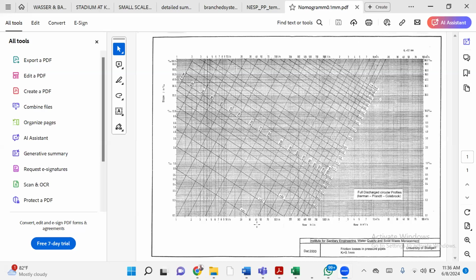Once I read this, I get 2 pipe sizes and receive 2 parameters from this. You will see that it's between this pipe and this pipe. I will choose the biggest, which is 200 mm. It means I need 200 mm to supply water to a 20 hectare district. And that is my primary pipe. When we start going down, those primary pipes will start getting smaller again.